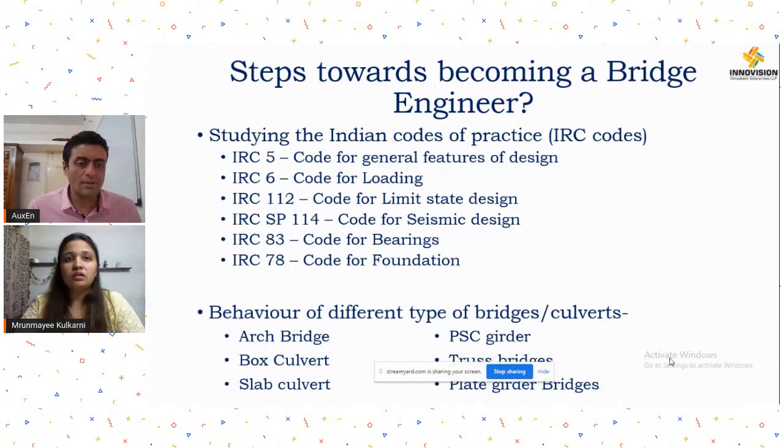So to make it easier, they have given some solved examples and everything. Because in these base structures, the stiffness of the structure changes from foundation to superstructure, because there are bearings in between. So the stiffness is different. So idealizing that stiffness and then calculating the time period is a tricky part. So that's why they have come up with a new code.